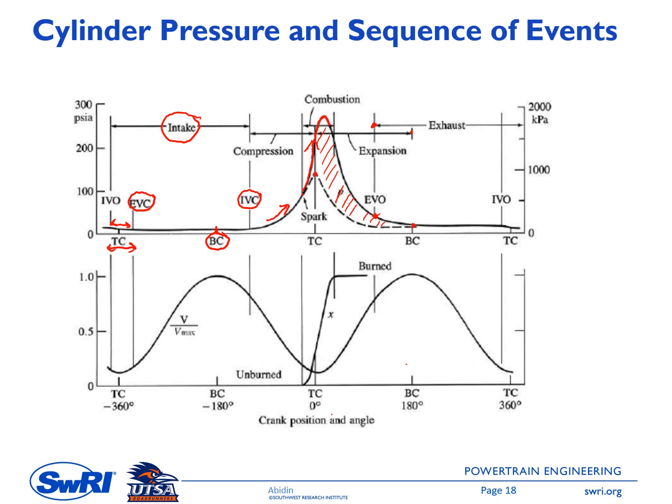And then the bottom side here is showing the change of the chamber volume. It is normalized by Vmax, the maximum volume of the chamber. At TDC, we have a minimum volume ratio here. And then at BDC, for sure, V over Vmax equals 1, because maximum volume occurs when the piston is at BDC. And then another chart here is showing the history of the fuel mass.